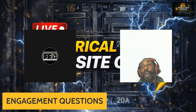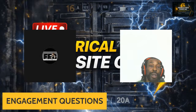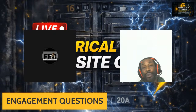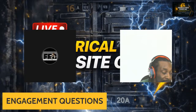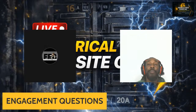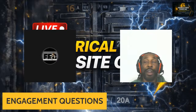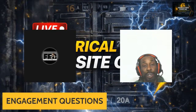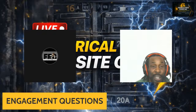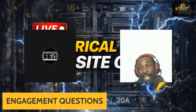With a 20 amp breaker, you have a 12/2 wire that's going to feed into the breaker. The breaker is going to protect that wire. Again, the breaker is there to protect the wire, protect the circuit, and not the device, as all of us get it wrong a lot of times.